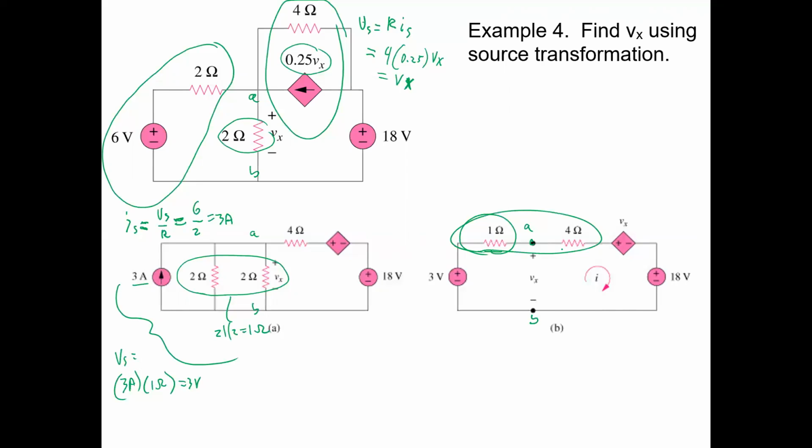Isaac: Can you still measure the voltage across two nodes even though there's no branch or element? Yes. Can't you just hook up your voltmeter to any two nodes in a circuit? It's the potential difference between those two nodes. That's what your voltmeter is going to tell you. It's really easy to do. And in fact, your voltmeter is actually a tiny load on a circuit. It's like a really high resistance, like a 1 mega ohm resistor. So it's not putting much of a load, but there is a little current going into your voltmeter when you do that. So you're influencing the circuit a little bit, but very little.